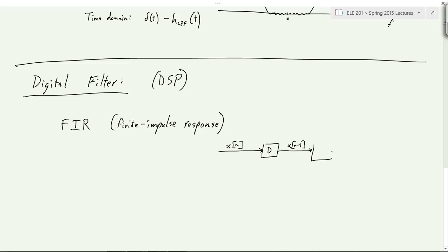Okay. Now let me have a series of these delay elements. I'll just draw 3 here. So what that means is we're holding on to 3 samples of the past. We're getting new samples all the time, and we're just retaining in memory 3 of the past samples. They're going through this block diagram. So this is x of n minus 2. This is x of n minus 3. Okay, so when a new sample comes in, it kicks the old one out of memory. All right. This is actually, in real life, the way that DSP processors work is they have some memory. It's longer than 3, some amount of bits that are a buffer. They read in samples, and as they cycle through the buffer, they overwrite the old samples.